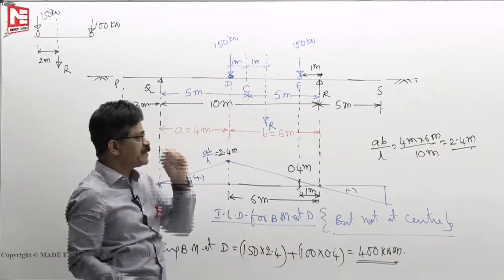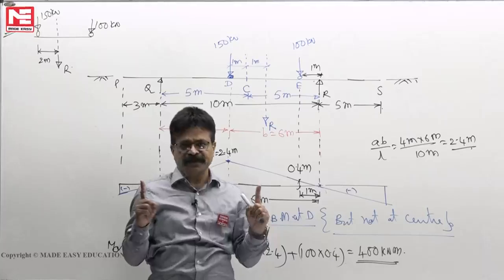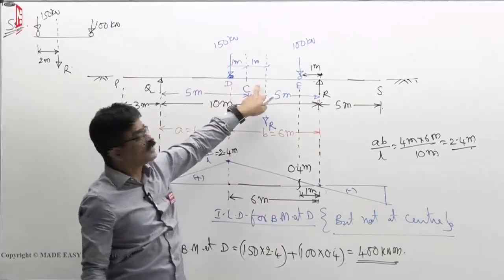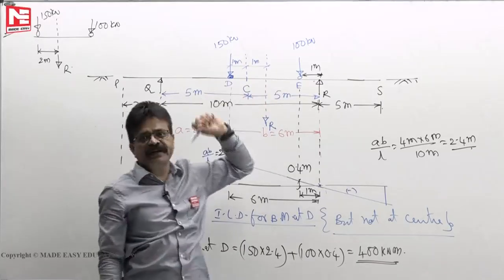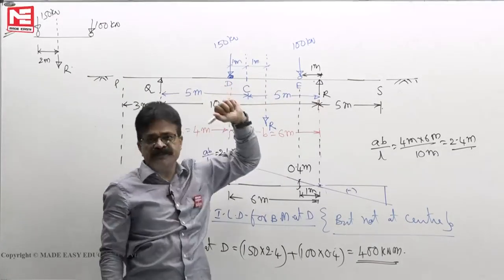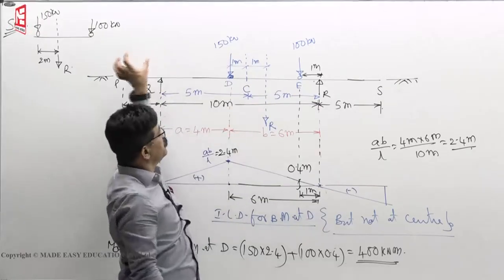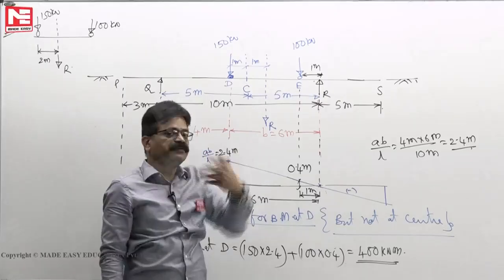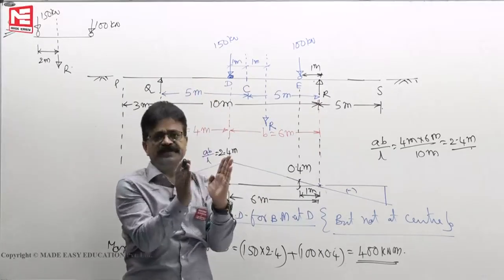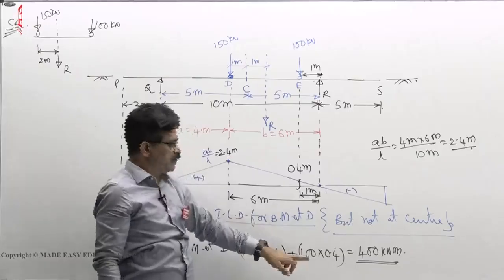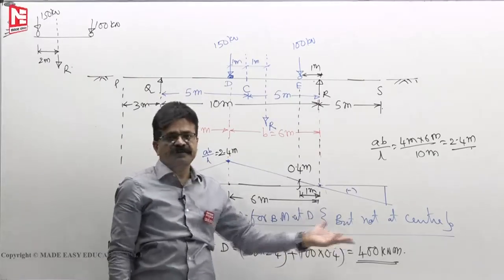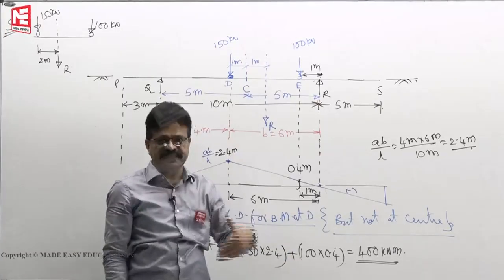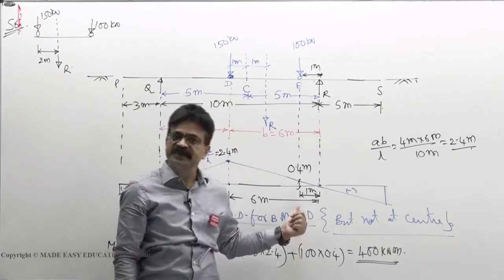Another paper what they have done was, you are given a simply supported beam, say of span 10 meters, no overhangs, but its section modulus is given, say 4 into 10 to the power of 6 mm cube. Then what is the maximum bending stress developed in the beam? Then what we have to do? Then first position the loads to get maximum bending moment. Once you know bending moment, you can find M by Z, then it becomes pure strength of materials. So, bending stress is M by Z, that we have to use to get the bending stress.